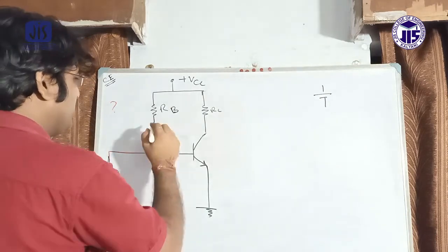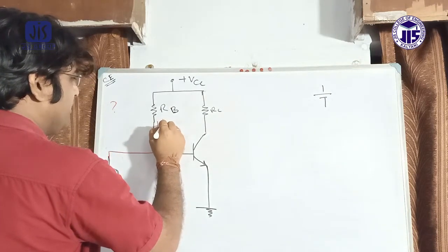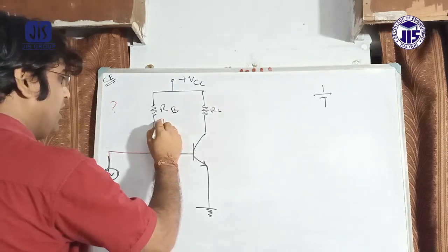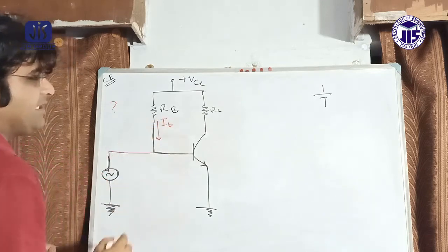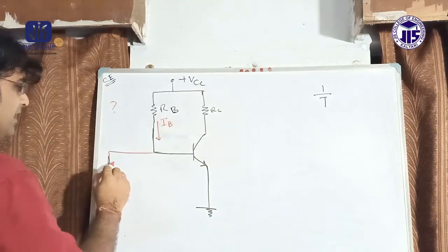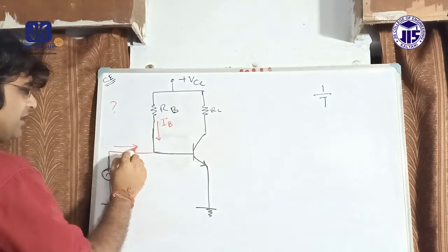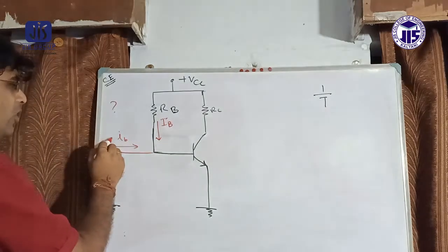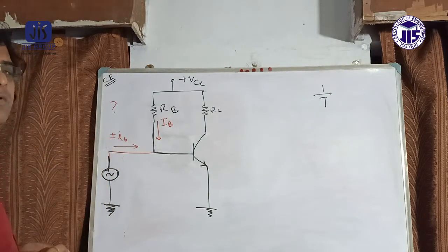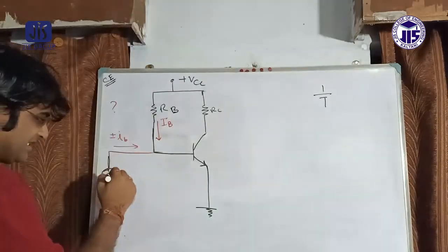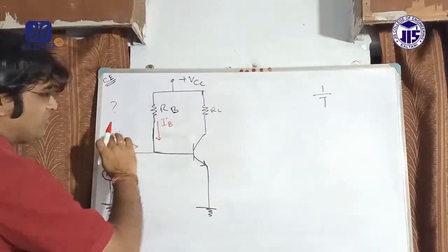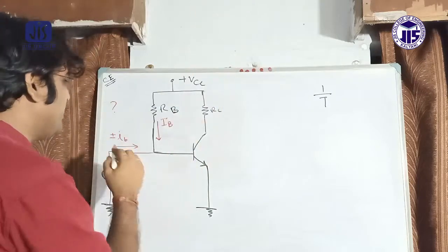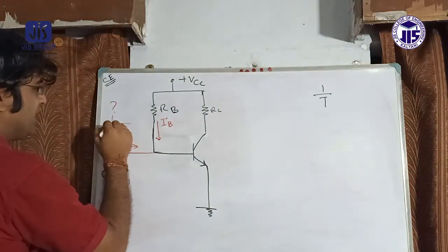We already know that the base of the transistor controls a huge collector to emitter current. So with the change of this IB, this IC also changes, with an AC nature. A small change of current in the base causes a huge change in IC. We can collect this change of IC, which means the AC nature can also be obtained through the capacitor.